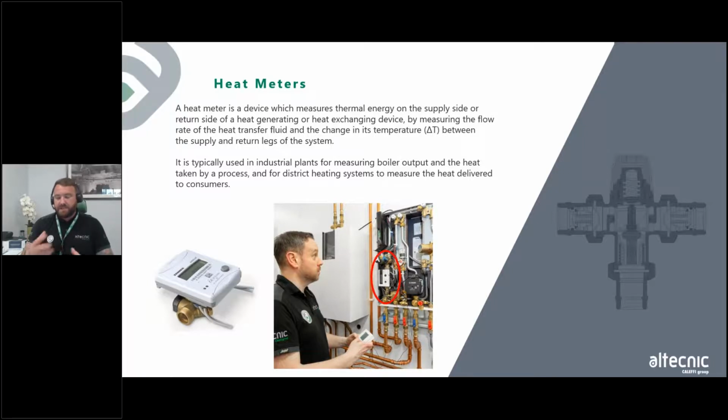A lot of people have a misconception that what you want to be doing is sending hot water back to the centralized plant because you don't need to use much energy to reheat it. It's not the way. We need to withdraw as much energy as we can using the plate heat exchangers. So the bigger the delta T, with the flow rate, the more energy you're going to use. If you're just whizzing hot water around, you're not taking any energy out of the system. So what you want to make sure is that the system is balanced correctly, and we're taking the right amount of energy from the system.